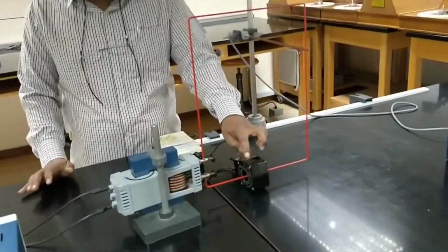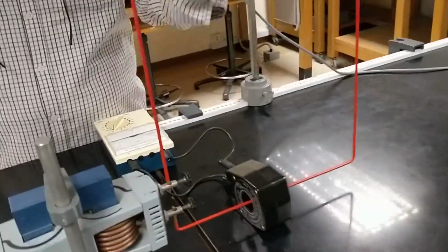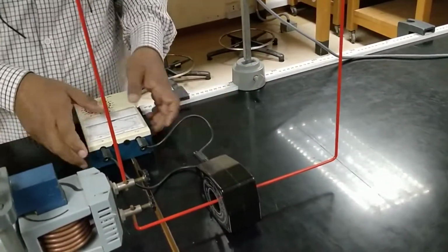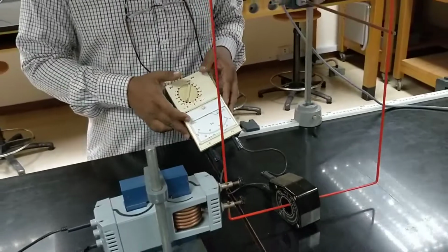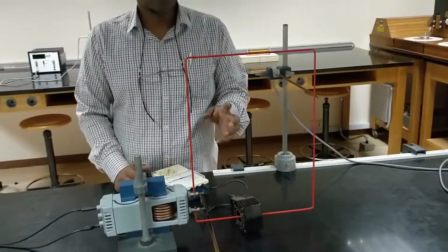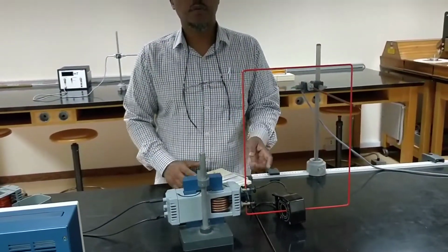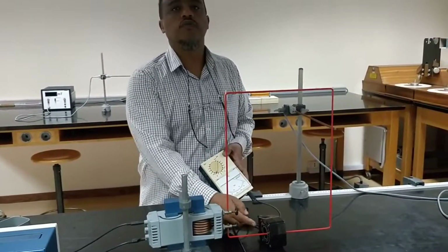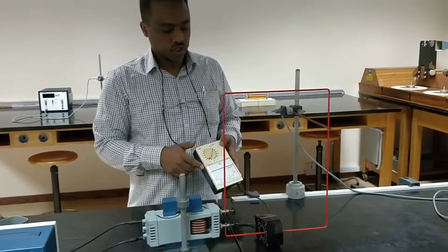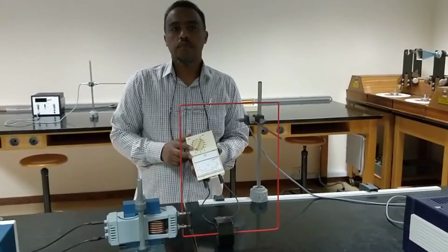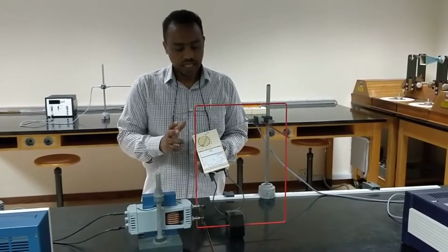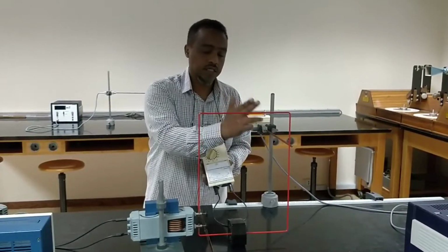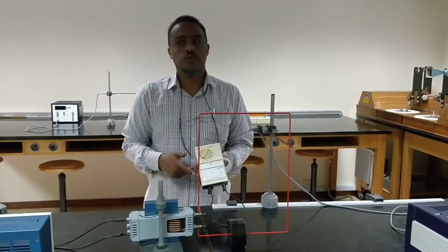Now this current transformer measures the amount of current that is passing through this, and the relation between the current that is passing through this and the current that will be measured by the current transformer is 100 times. So if 100 ampere passes through this, you will be measuring only 1 ampere, and the multiplication will be, of course, the 100 that we have here. So we are using just a regular ammeter to measure the current, and the current here is simply 100ths of this current that is passing through the wire.